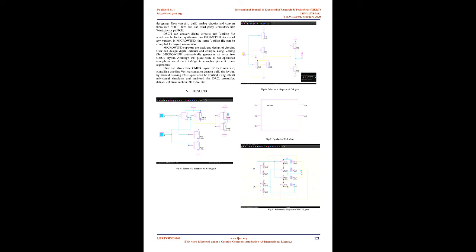Partial product generator. Function: the partial product generator generates the partial products to be added with a Wallace tree. Algorithm: the partial product generator uses the table for each multiplier bit. Depending on the value of MD or MD' and MR or MR', it is assigned to the partial product. The 4-bit value is then extended to the 7th bit for appropriate sign extension.